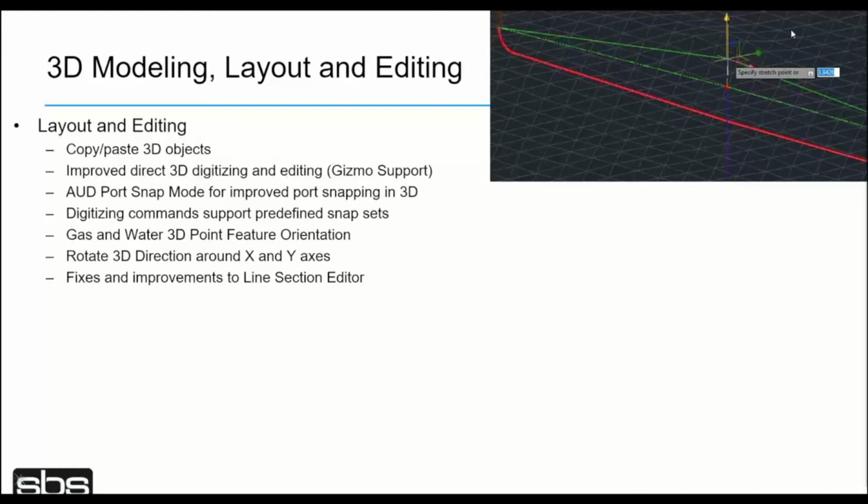But in certain cases, the AutoCAD gizmos provide a very streamlined, simple way to work with 3D geometry. Previously, they weren't very usable because even if you edited it in 3D with these, the system didn't really support direct 3D editing. But now with direct 3D editing supported, these tools provide a much simpler way to do things like change the Z elevation of a segment ground reference line.